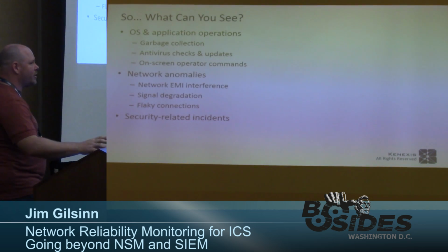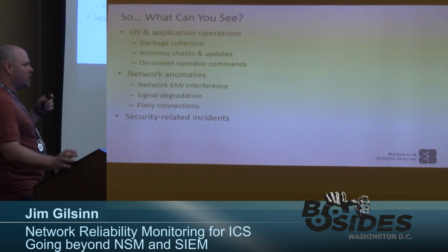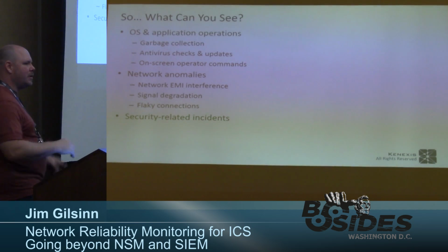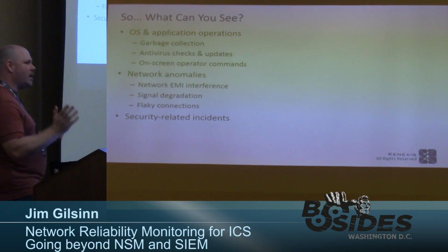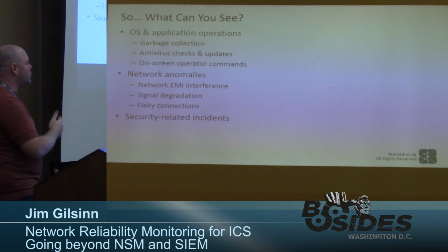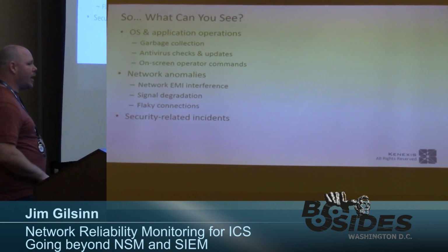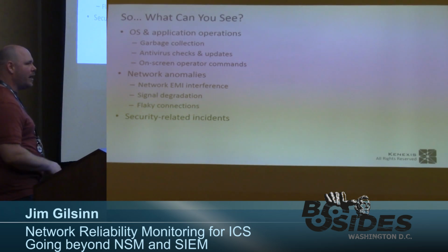On-screen operations are another one of those that causes weird things to happen. Sometimes, especially Windows, will just go off into la-la land while it's waiting for some process to happen on the screen. You click the button and it just decides not to react. So that's another reason why a lot of times the vendors will not allow you to install things on there that they don't know about, because it could interfere with their HMI software or whatever software they've got.